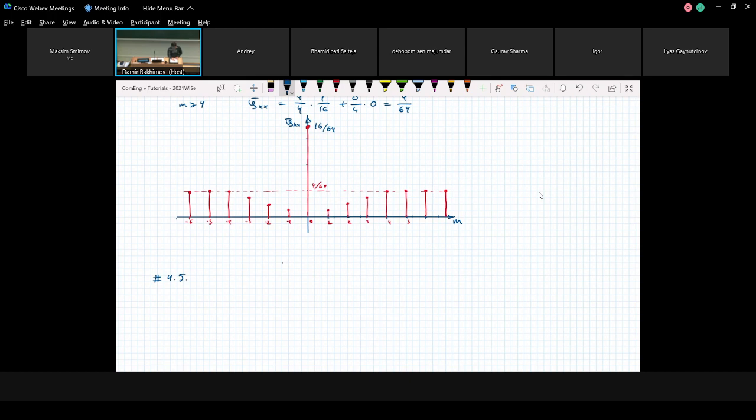And we need to determine the autocorrelation function and power spectrum density of the output signal. And then we need to determine the RMS value of the output signal, the root mean square value. So we have a rectangular window, f divided by 2 fg, as our transfer function. fg equals 5 megahertz.